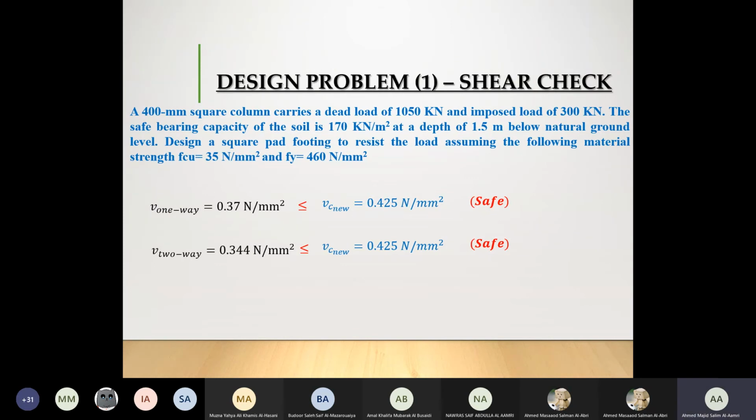Are we okay? So if your slab fails in deflection, or your foundation fails in shear, you need to use your logic to decide. The regular decision is to increase the depth or to increase the reinforcement. Are we okay? Do we increase both, or do we choose depending on the situation? Why would you choose both?